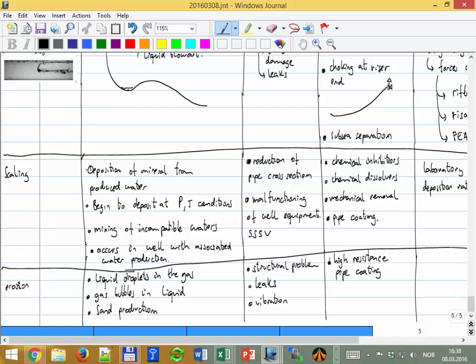A cover is a protection layer inside the pipe to avoid erosion, or reduce the rate of erosion. If you see that you have a very severe erosion problem, and there is a very abrupt change in direction or in geometry, then you try to smooth that geometry. For example, if you have an elbow, you smooth it, so you are sure that the velocity at which the sand particles hit the wall is not high enough to cause problems. So, modify geometry.